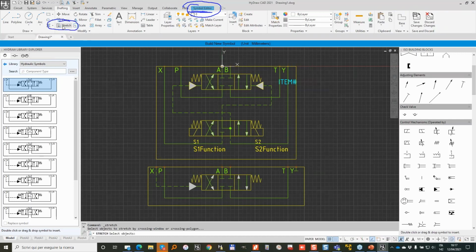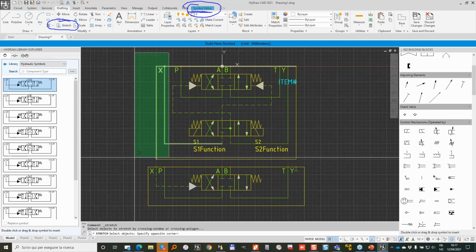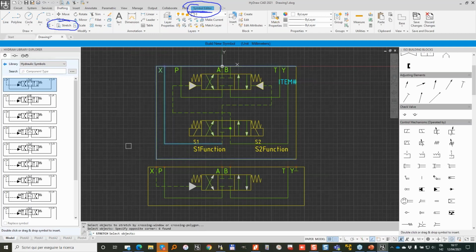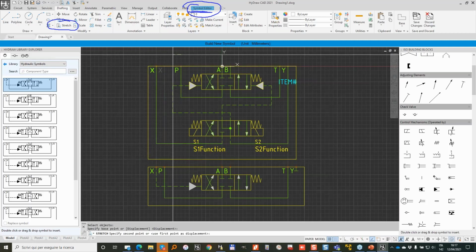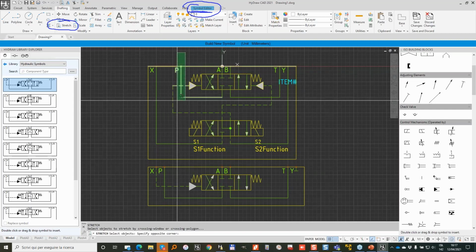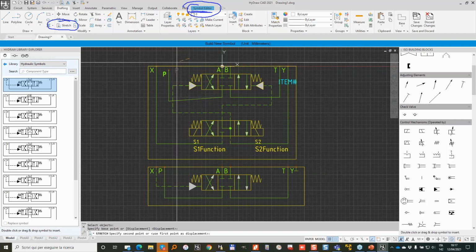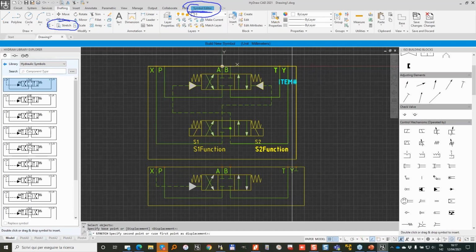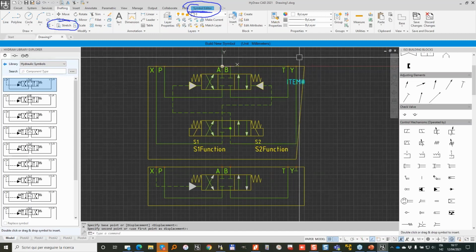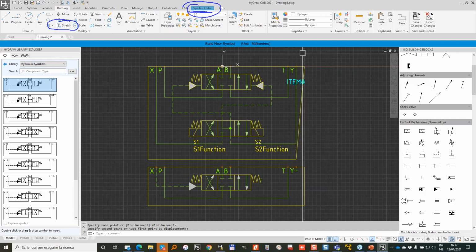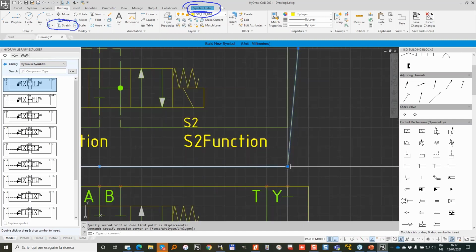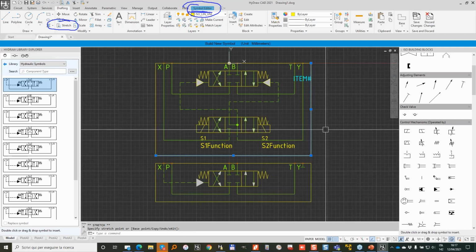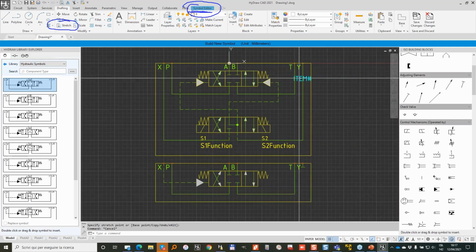So you stretch, you select with a window from right to the left part of the diagram, confirm, and then we make a modification. Same here. Please pay attention to what I select. So in this case, I select only the vertical P line, so that the change is only applied to that vertical P line. And same here. As you see, I didn't select this corner, so the stretch has modified my symbol. So in this case, it's very easy to fix. I just move this corner. Otherwise, you need to pay attention to how you select the items.